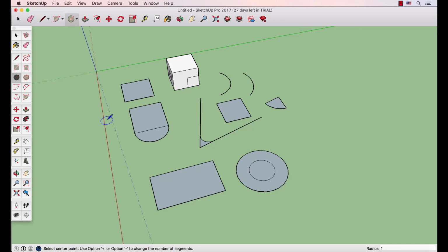In the same way, we can form a polygon by clicking on the Polygon tool on the toolbar. After defining the center, we define its radius and hit enter. We can also change the number of the polygon's sides. We draw a polygon, we type 9s for a 9-sided polygon, hit enter, type its radius and hit enter again.